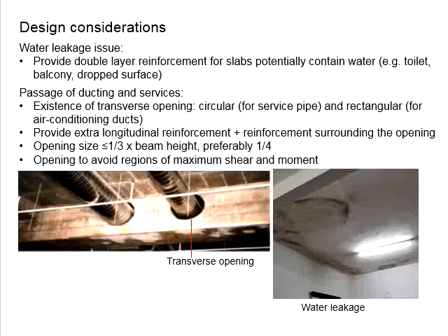In the previous videos, we mentioned the practical considerations in terms of the water leakage issue, where you need to provide additional reinforcement bar in order to control the crack width within the concrete, so that the water does not penetrate through the reinforced concrete slabs. We also mentioned that you need to observe the architecture drawing in terms of the intended flow path for the